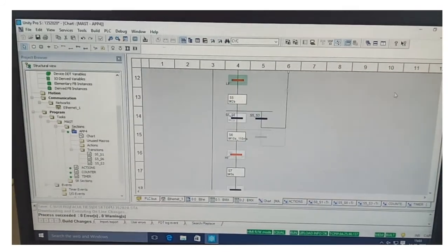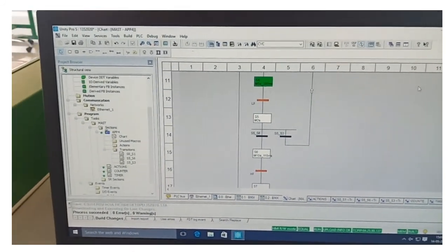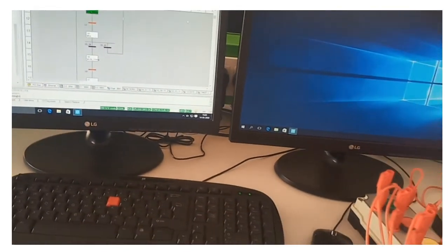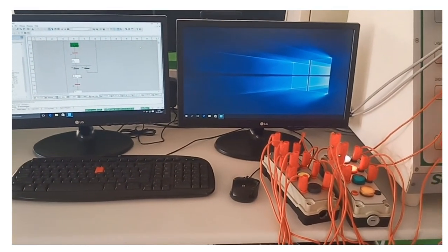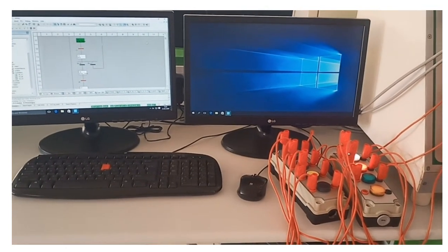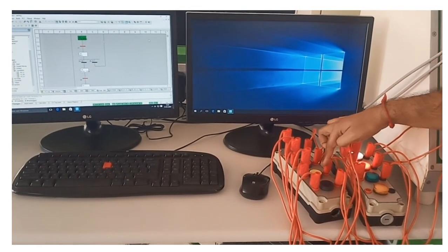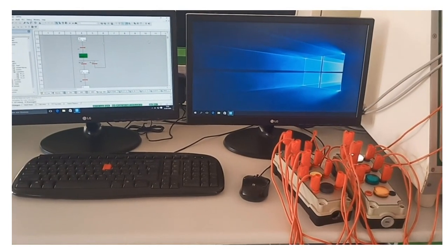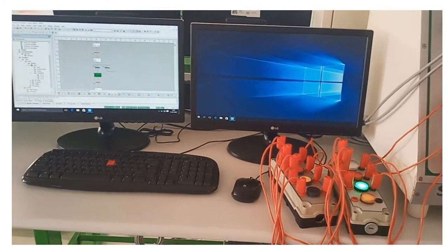In the intermediate position, the cylinder will start to extend. So it will extend up to the low position. Meantime, it checks for the cycle also. Now the cycle is 1 plus 1, 2 is yet to complete. So it comes to the low position and it waits for some time for drilling, and the cycle is completed for twice.